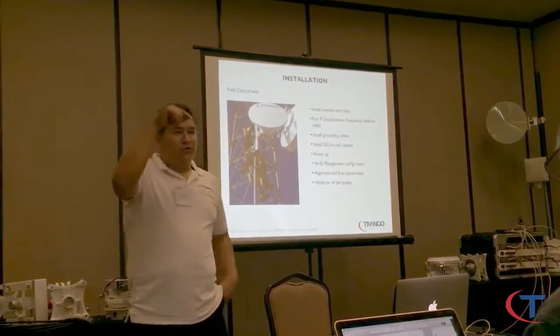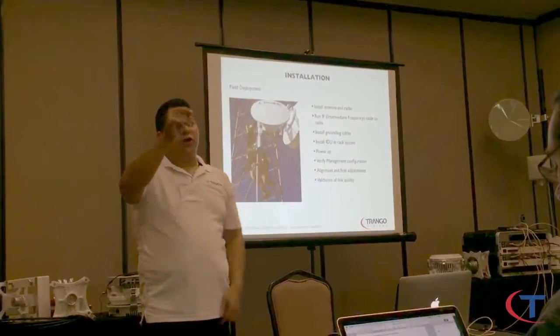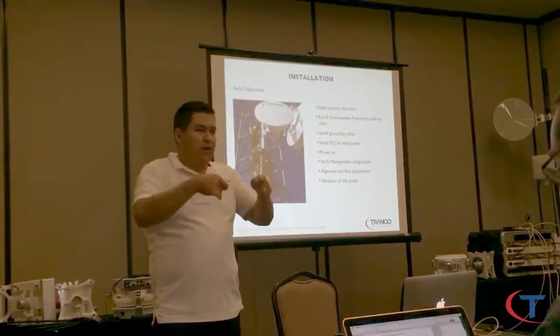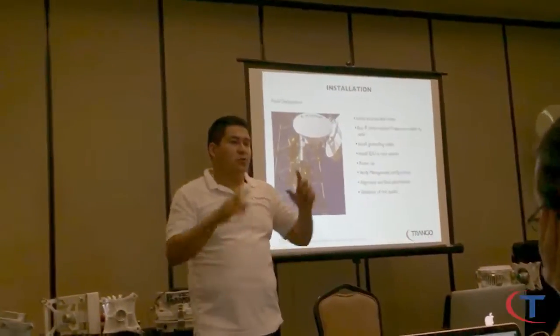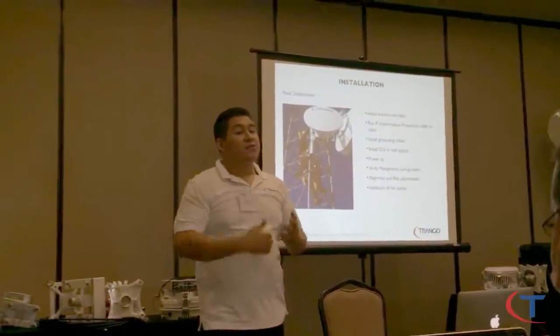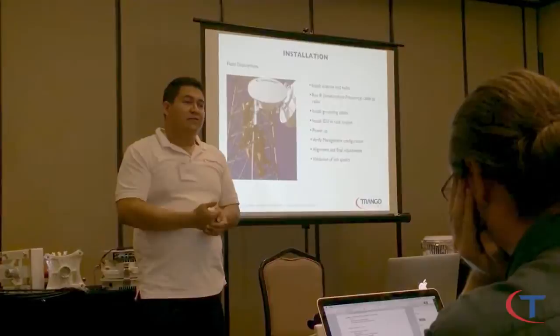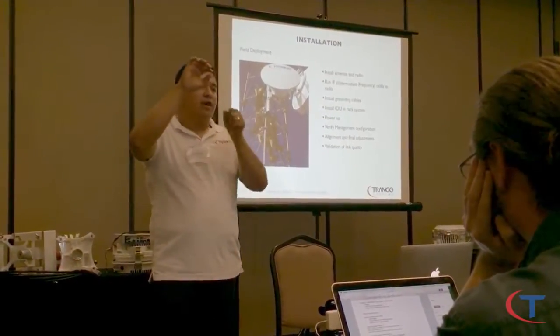No, you can actually ground it at the tower. So it's going to be literally the ODU, and then you ground your green cable, basically your thick cable, to the actual structure. That's grounded itself. So you don't have to run it all the way down, just to the grounding block there. And then there's another extra feature there, a polyphaser. So polyphaser, it's the inline protection from the ODU to the IF cable.